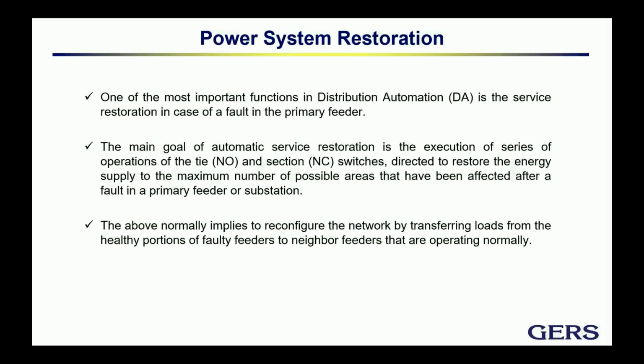So the term system reconfiguration or distribution system reconfiguration is basically the operation of section switches and tie switches. I mean, the opening of closed switches and the closing of tie switches in order to recover the distribution system after a fault. That is basically what we will deal today, and we will consider how to do the setting of this type of systems, which of course is becoming a very comprehensive action.